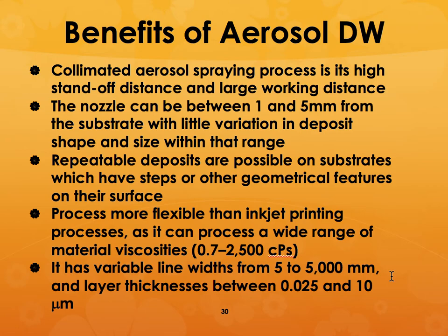So what are some of the advantages? You can put it down from a high standoff distance and large working distance. You can have the nozzle between 1 and 5 millimeters with little variation in deposit shape and size. And it is much more flexible than inkjet printing. And you can process a wide range of material viscosities.